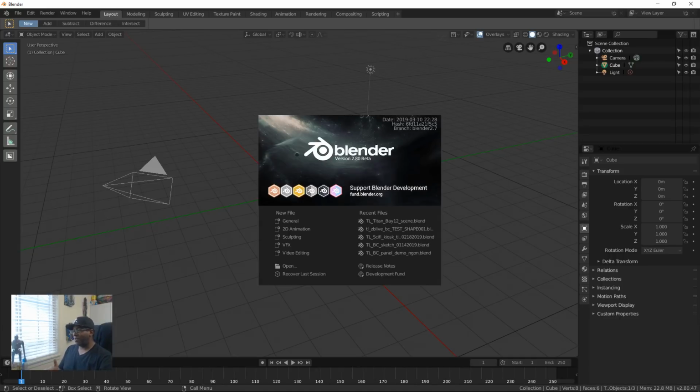So if you catch the half movement of something like somebody running, and it's 3 steps to the run and they're this way, and you catch it right at the peak and hold it there, you can actually export that out as an OBJ, put your maps back on, and then you have something that's posed, you know, like in a more natural running pose than you would probably try to do by actually just moving the rig and the actual character around. So you can use it as a nice starting point to really get a nice pose, actually.